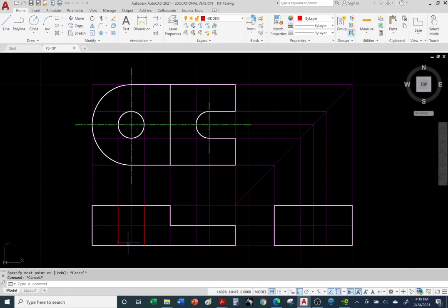All right, so now let's create an axis. You do need an axis. So from this center, you need to draw a green center line to represent the axis of the hole. Let's go back to the green center layer. Use the line command. I know I have to follow the center of the circle above, right? Click. Okay, good. You don't want to overlap the two views, so I need to make sure there's a space between the two green center lines. Click and hit escape.